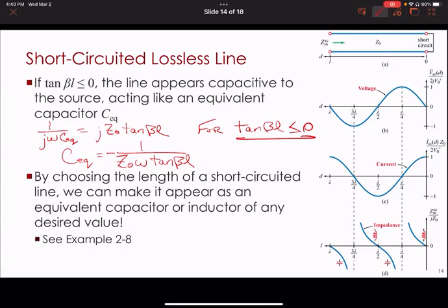When you do your circuits classes, you just kind of go, all right, I need a 1 picofarad capacitor, and you just get it and stick it in the board and assume that that's 1 picofarad, right? If you pay no attention to it and you're at these high frequencies where all these concepts are important, not only might it not work as a 1 picofarad capacitor or whatever, it might actually behave as an inductor.